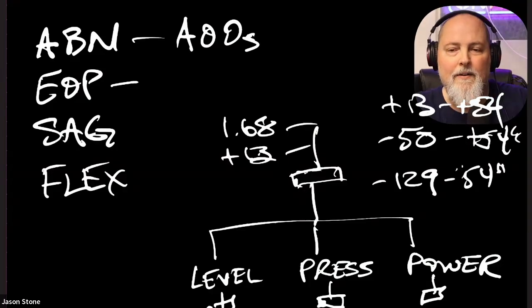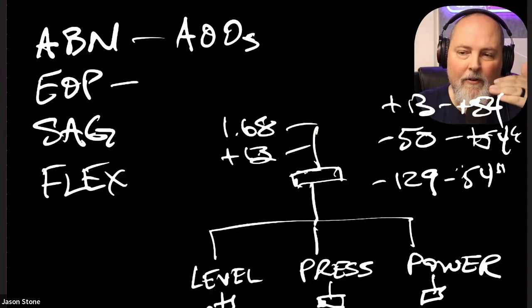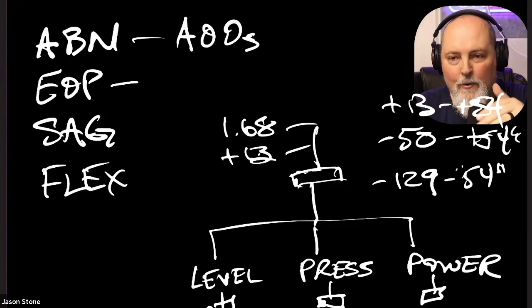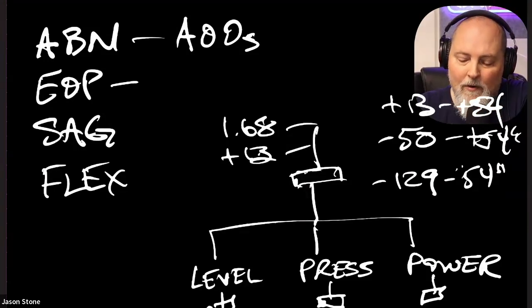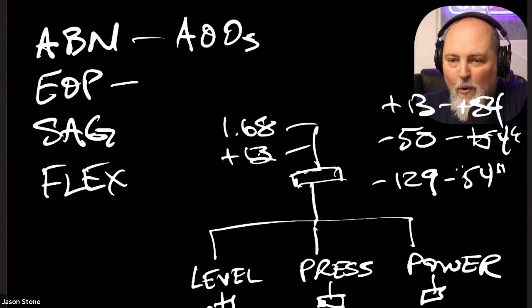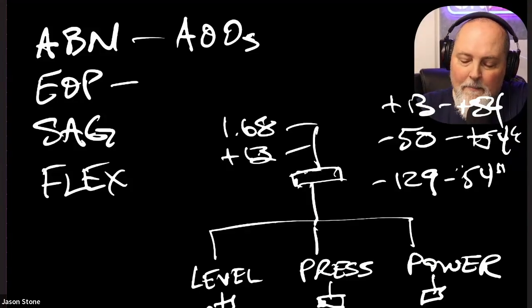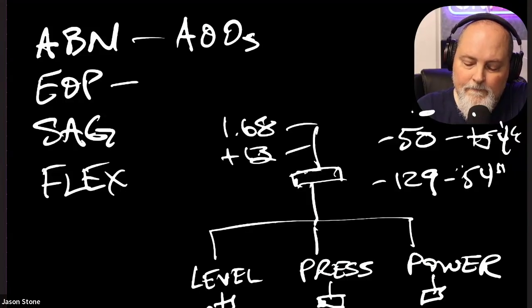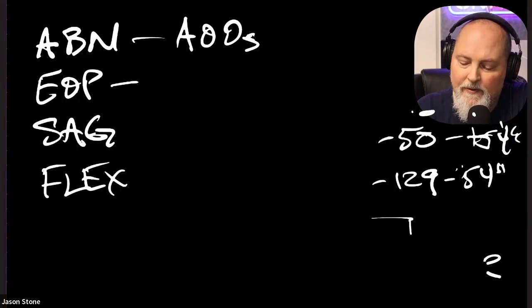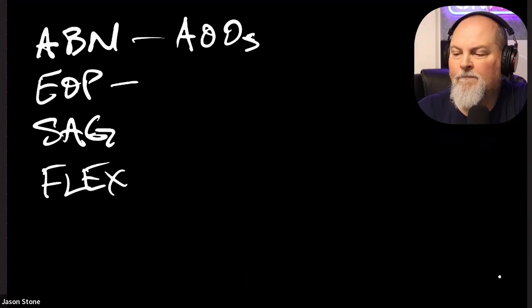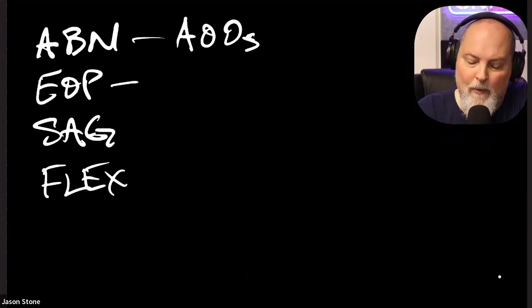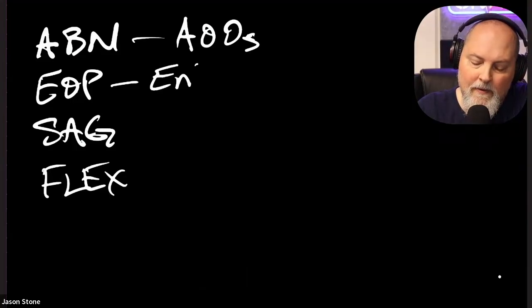And then it gives you systems, and it tries to give you, hey, use this system, do this system, use this system. So these are symptom-based flow charts. It's not a book that you open up. These aren't procedural steps. They're just symptom-based flow charts. And the other thing I wanted you to know about that is they're activated when plant parameters exceed protection system set points. So they have entry conditions.